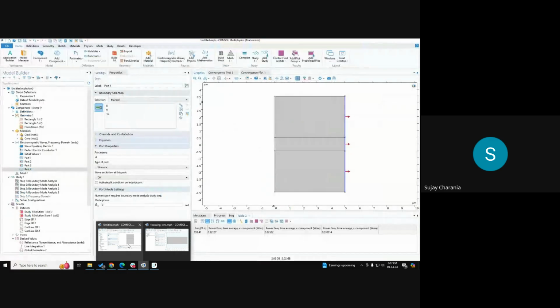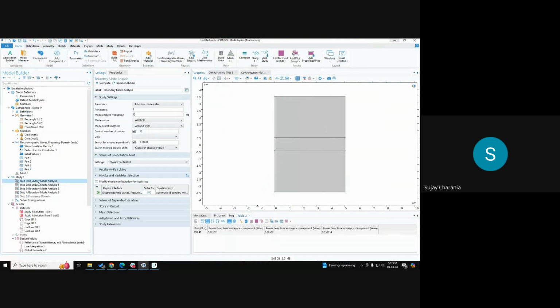Because if you tell it to find only one mode, the fundamental mode, and find power, and then you say find 10 modes and find power, when you're finding 10 modes some power has to go to the higher order modes, and you will have a certain reduction in the fundamental mode. On the other hand, when you ask it to only find the fundamental mode near the refractive index of the core, it will certainly have a different value of the power or the values of field. Will that make a difference, or will it not?